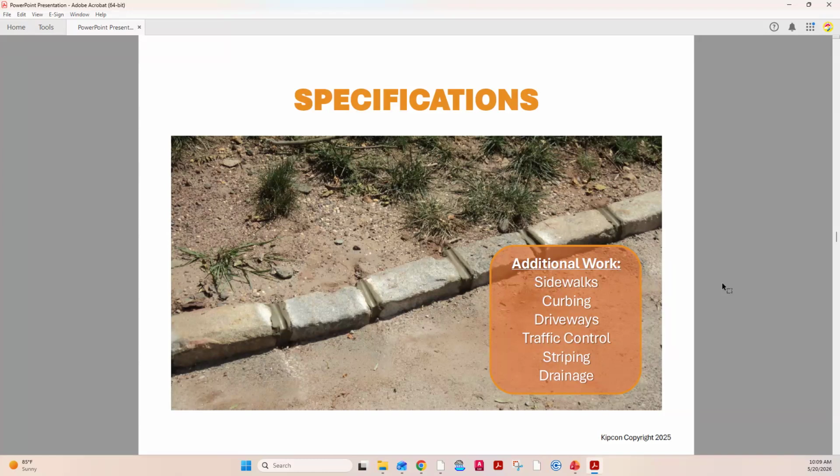It can stress your roads and cause them to deteriorate more quickly. Roofing material is very, very heavy. So if you have a roofing project that needs to be done and you have an asphalt project that needs to be done, you want to get those roofs done first. Same thing with driveways. If you are going to do a roadway project, take a look at the driveways. Do the driveways need to be done first? Maybe some of them do, maybe some of them don't. But you want to take care of any asphalt, any roofing projects before you do your main roadways.